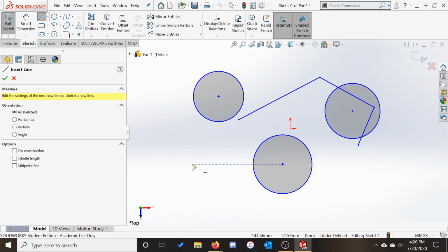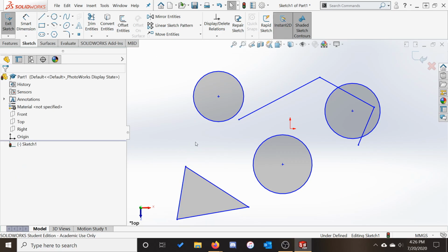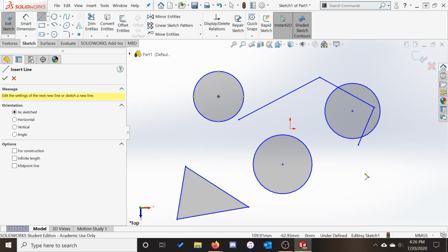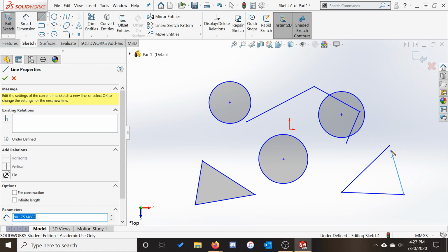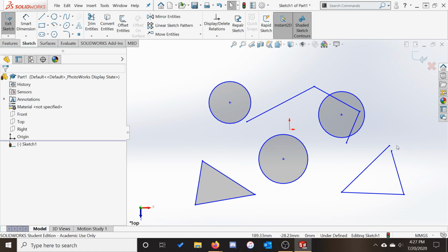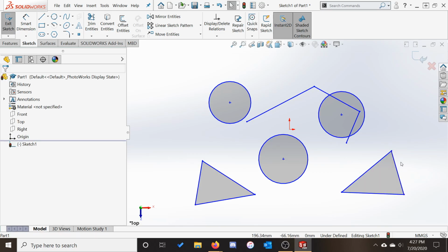While you are sketching, whenever you close a shape, or draw a shape that perfectly encloses an area, it will shade the enclosed area with a blue fill. This will only happen when a shape is perfectly closed, so if any endpoints don't exactly match up, it won't count as a closed shape. You can deselect your tools via the Escape key, and left-click drag to reposition endpoints to match them up better, which may fix the issue.